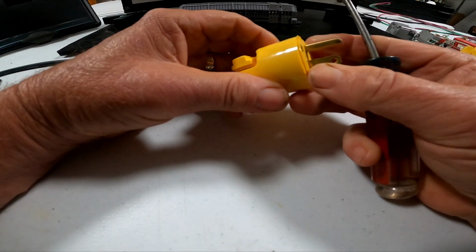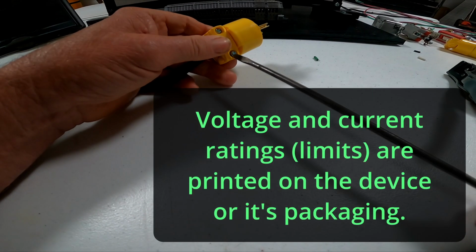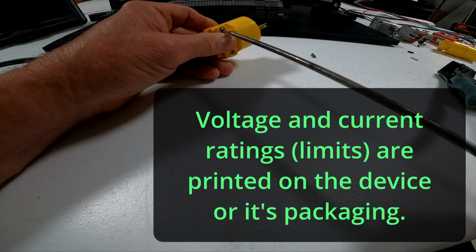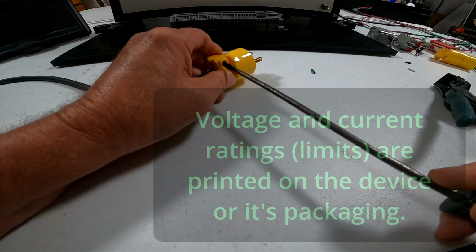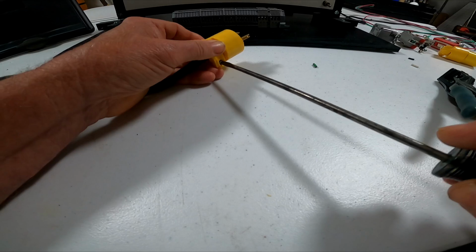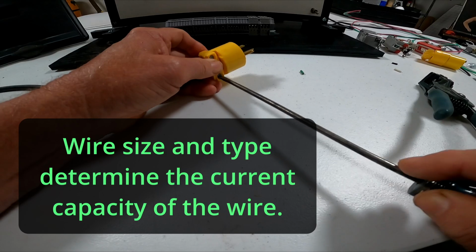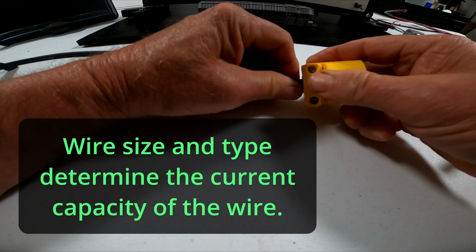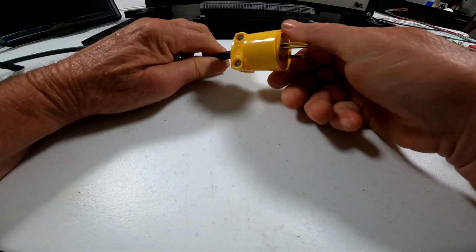This is a 110 volt, 120 with a 15 amp capacity. That is what this plug is rated at, so you should not run more than 15 amps through it. And as we will learn later, you must match the wire size to the current. In this case, we are using a 16-3 rubber cord, which means it has 3 number 16 wires in it, which is capable of carrying the 15 amps. Now we give it a good tug, and there you have it, a complete plug.